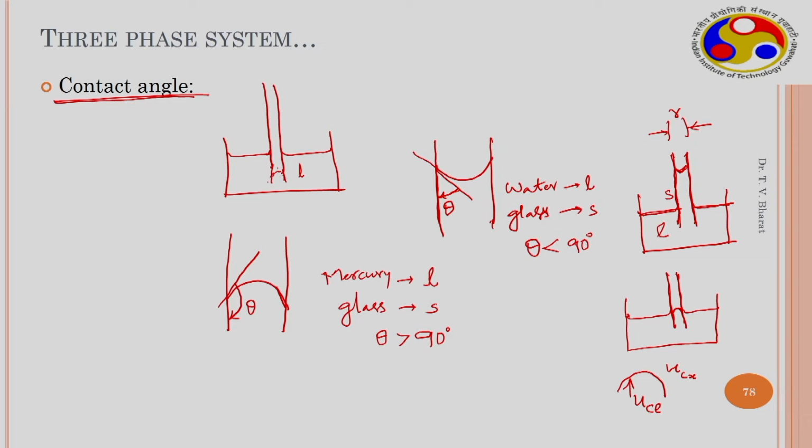So the liquid surface interacts with the solid at some angle known as contact angle theta. The nature of the meniscus curvature, whether it is concave or convex, indicates whether the fluid is wetting or repelling. In this case the fluid repels from the surface, so it convexes up like this, or is concave in the liquid phase.